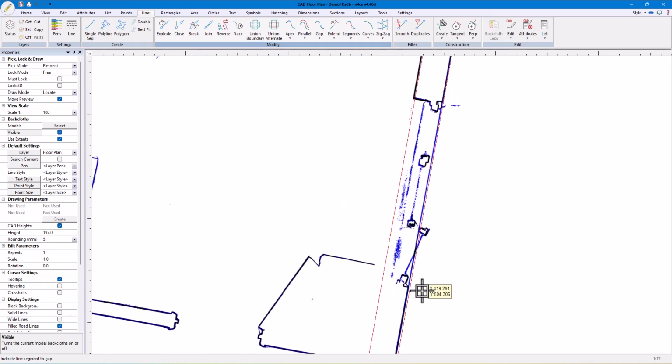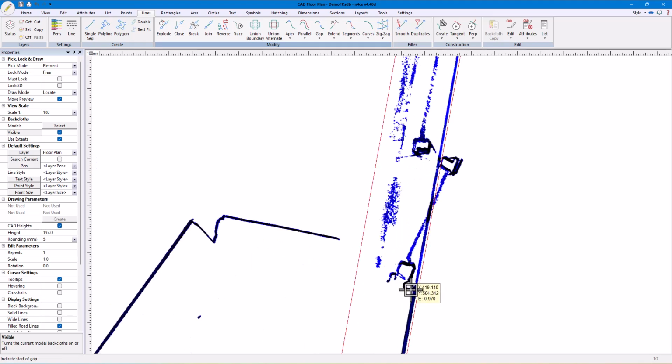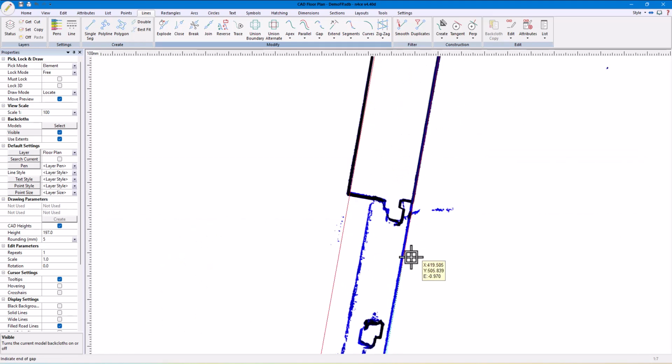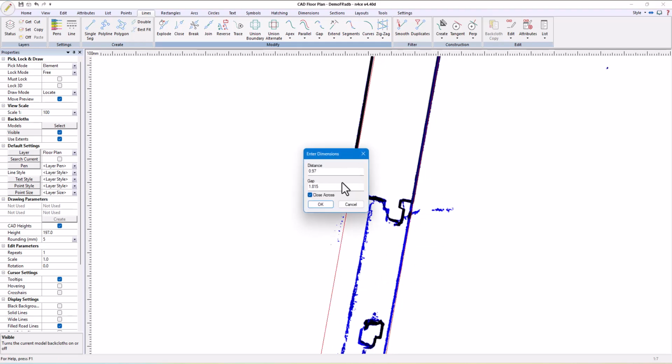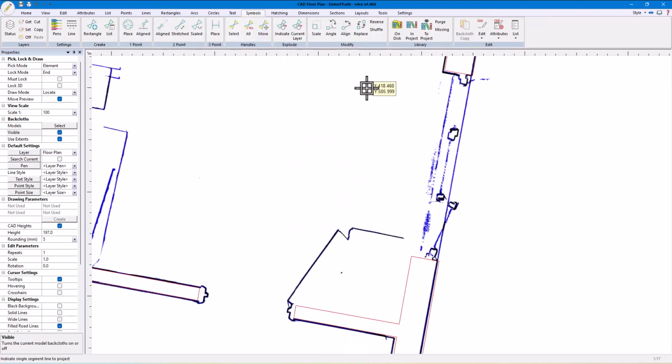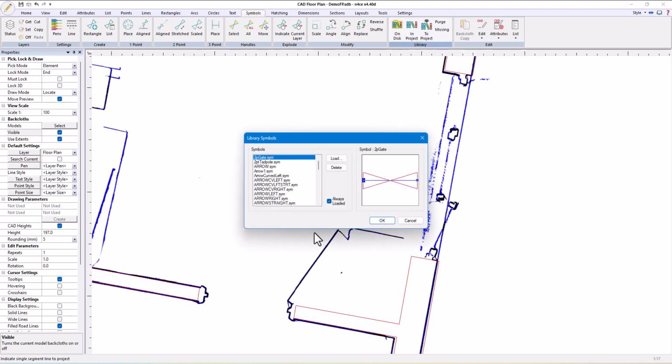into their respective openings. For the windows and doors, we will use pre-existing symbols in the symbol library. If you do not have them, you can import them from existing floor plan drawings as blocks, or just draw your own. For this floor plan, we will load in doors opening in and out, plus a double window to start. Note, these are 2-point symbols. They have an origin and handle.